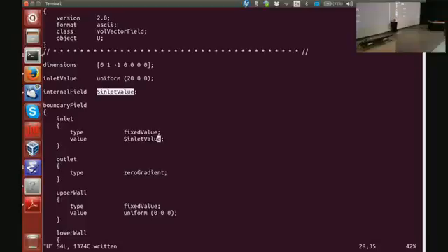Okay, so in foam, we want to use a boundary condition which will do the same, but we cannot talk about outflows and inflows at the boundary because the library doesn't know what equations it's solving. Okay, so for that we will use a special boundary condition called inlet outlet. What that does is it says if the flow is going out, use the zero gradient boundary condition as normal, which is what I would have here at the outlet boundary. But if the flow is coming in, then use the fixed value to a certain value. Okay? So let's just change it.